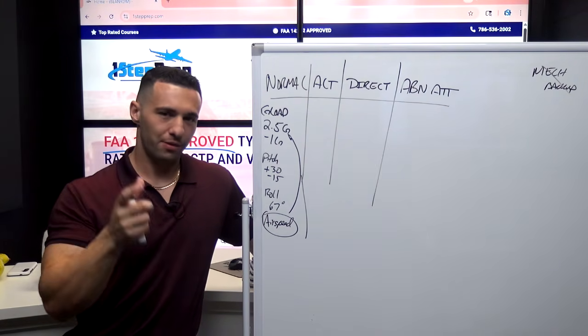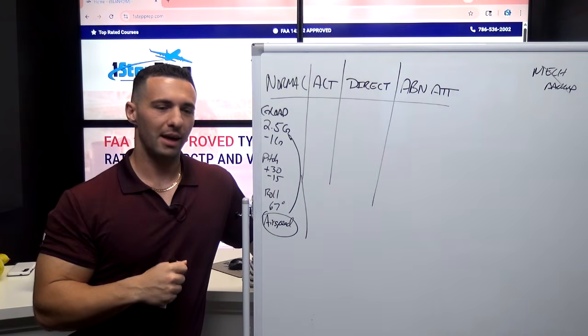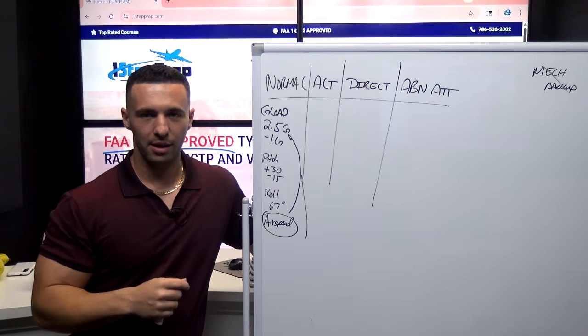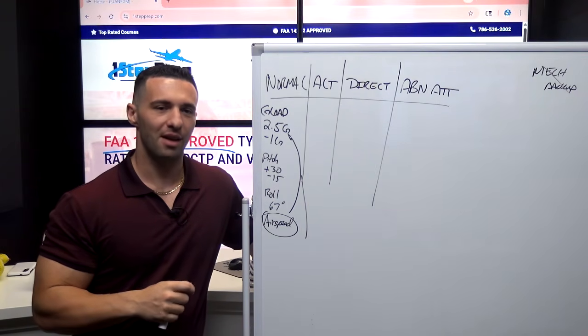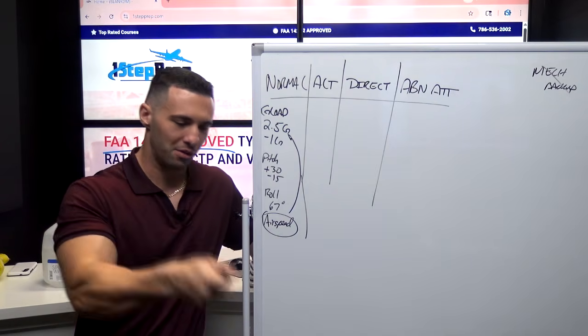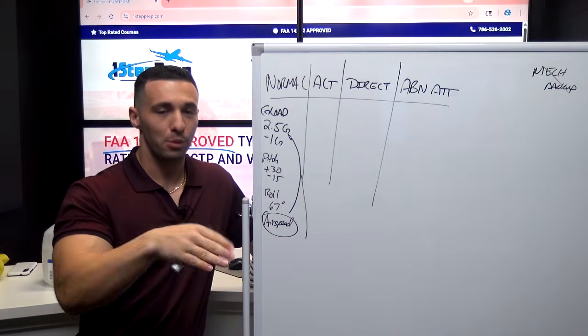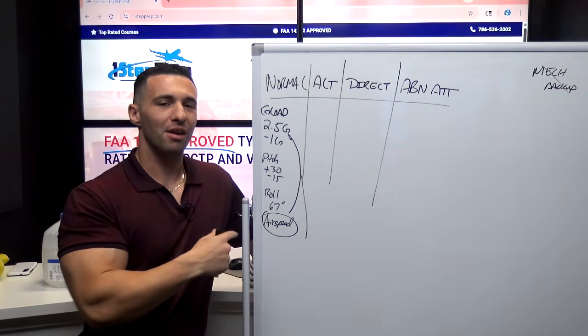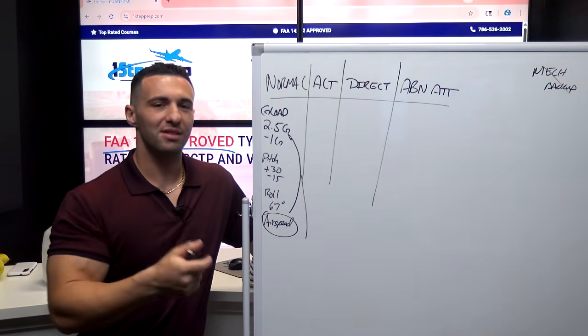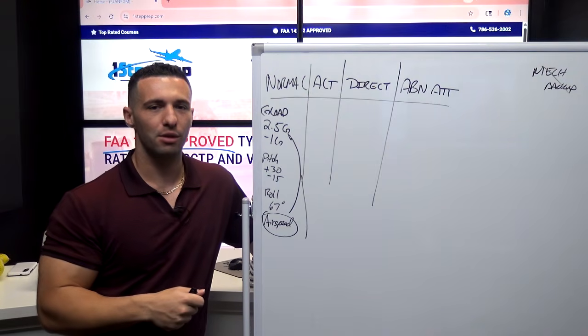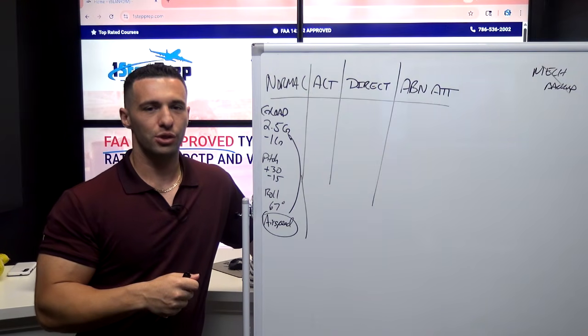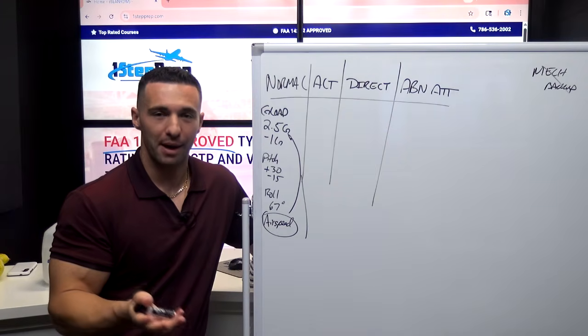But the challenge would be if you get a TCAS RA and it's somewhere maybe in the flight levels, and it's a descend RA, descend. So autopilot off, flight director's off, you start nosing down, you run up against the overspeed protection, which inevitably will drive the nose up. But because we have this additional plus 16 knots, it'll let you bury the nose down a little bit further in order to help in that particular scenario.